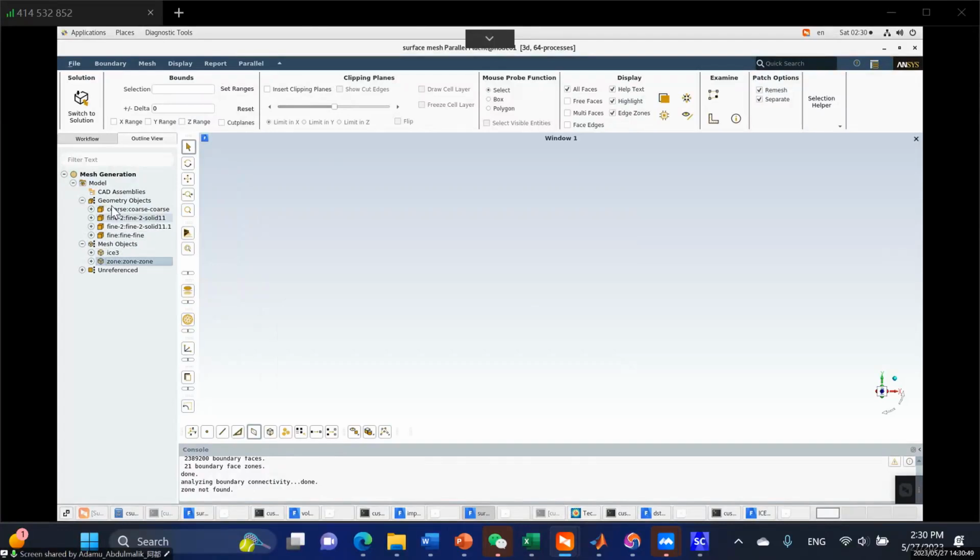This BOI is going to be here because we said we don't want the BOI to be meshed. What we want is to mesh only the environment it covers, the area inside it. But we want to mesh the train model and the computational domain. That's why we did this.